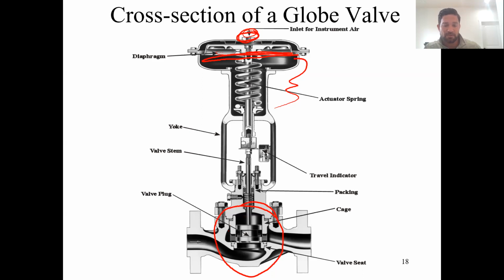The size of the body is going to determine how much fluid can flow through the system as it relates to the change in pressure from one side to the other. And then also the shape of the valve plug is going to determine how the flow responds, or how the flow changes as this opens within the system.